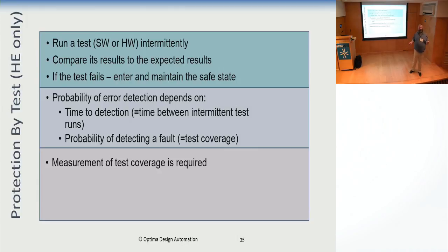In practice, you don't get 100%, and structural tests require rebooting the part before and after. Sometimes you can't afford this reboot. You go to functional tests. Functional tests have limited coverage. You don't get 100%, so you need to take account of how many faults your test misses, and then for that you need a measurement of the test cost.